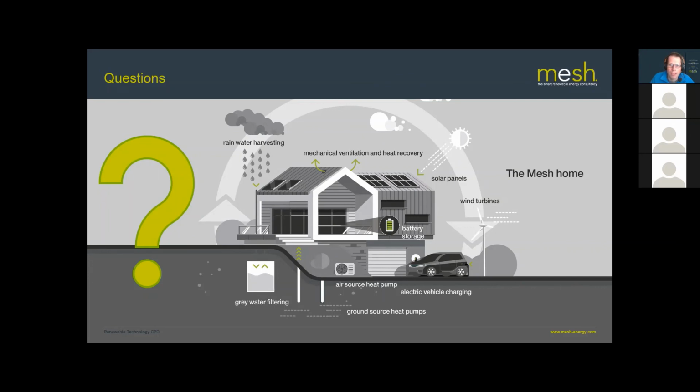Is there any fire risk? Richard asks about fire risk associated with inverters and equipment. There are some risks with PV, and if you Google it, you'll see that most fires with PV come from arc faults. That's one of the things that the safe DC system that SolarEdge offers, or microinverters, address. That's one of the benefits of those types of system.